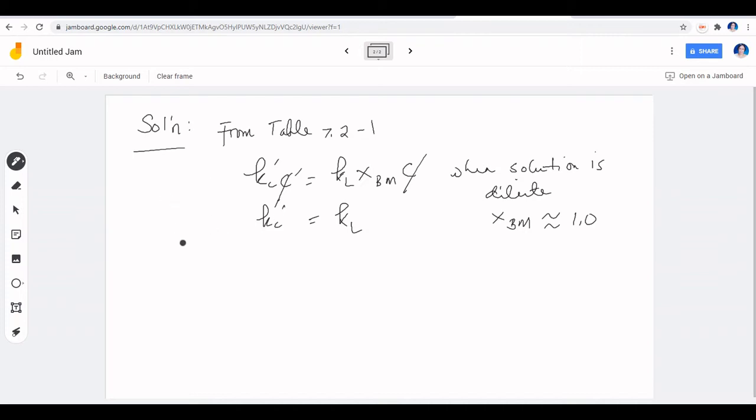So our Reynolds number is given by the formula. Actually, the original formula for the Reynolds number is diameter times velocity times density divided by viscosity, that is, D V rho over mu. Now, in our case, since we're not on a pipe or a sphere, this diameter will be the length of the flat plate. So this will be L V rho divided by mu.